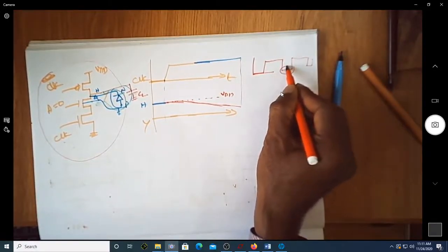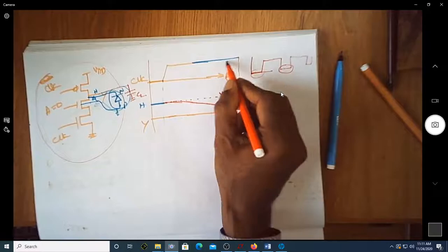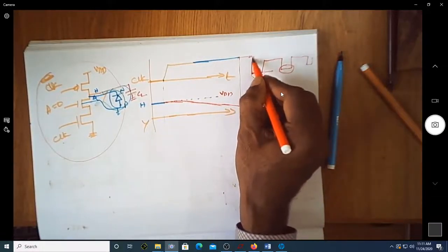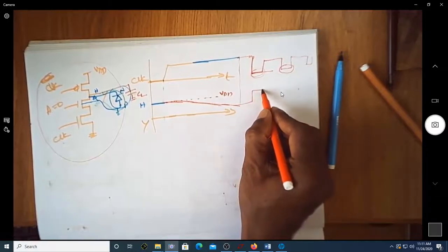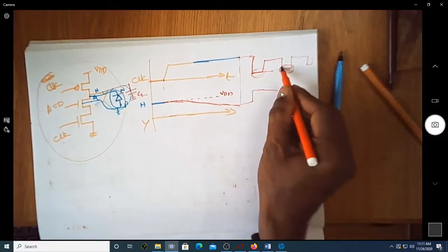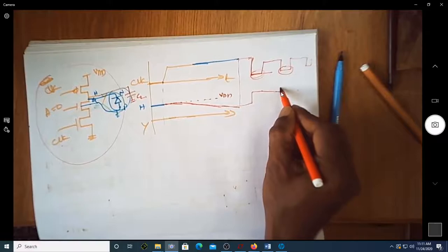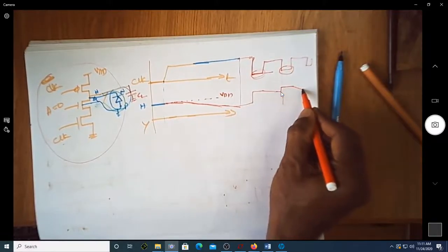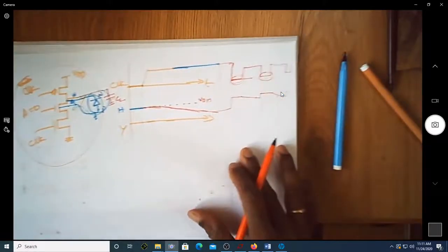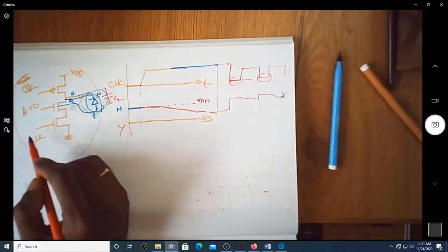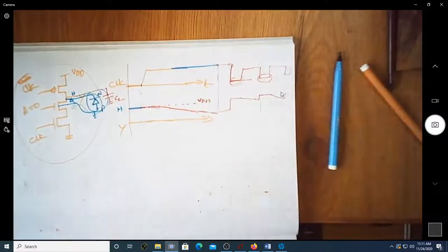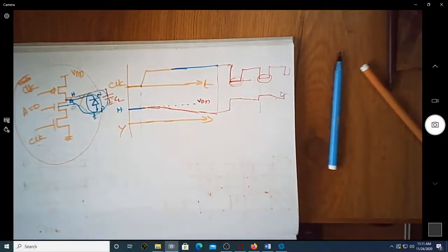So this pre-charge will make sure that, assume that if I'm just continuing this, can you see here, whenever it is pre-charge, this goes high. So this may slightly drop here, and because you are doing the pre-charge, it will again go high. Can you see this keeps happening? So this is a type of process that will be done for this particular dynamic logic implementation.